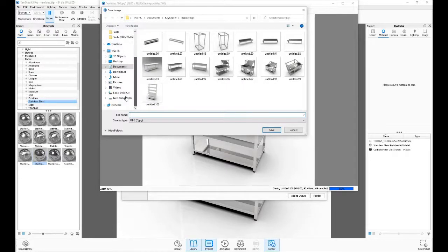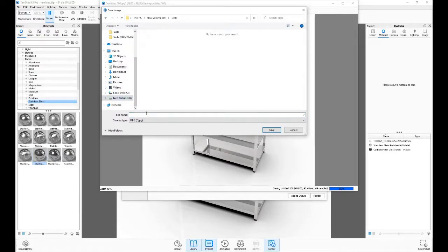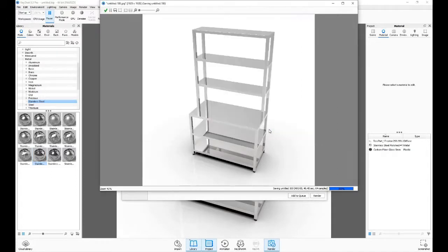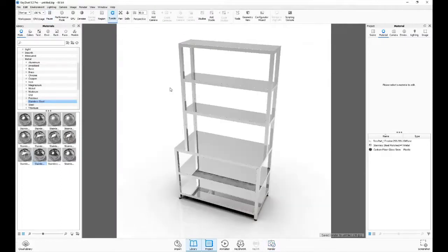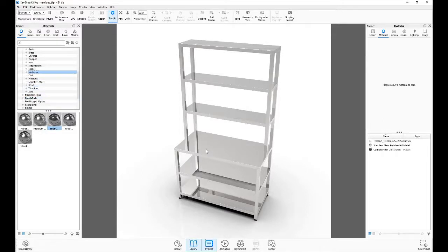Now for this file name, I'm going to do the project number. I'm going to go ahead and type this up, and I'm going to put in quotes, space in quotes. So it's got the project number and then a space. Then I want to grab the inputs for opening width. So that's going to automatically put the number in there for the width. And then I'm going to add some more text.